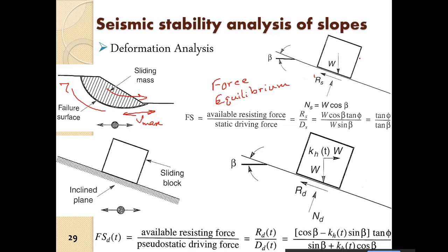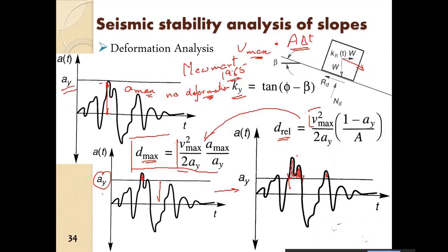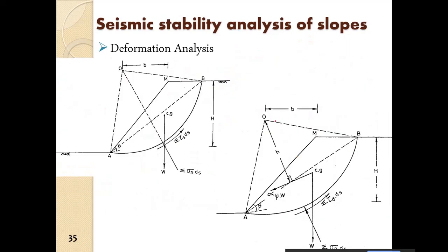So all the forces are summed up, stabilizing force by destabilizing force, static case, dynamic case. Newmark 1965 also gave a similar concept for moment, considering the moment in the slope.